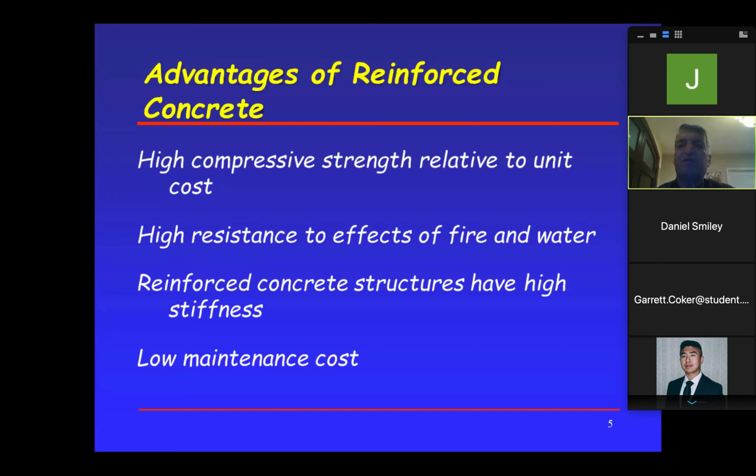And that's unfortunate for me because I like concrete. I'm a concrete guy. So we went ahead and built it with steel. Because at that time, China was booming and they were buying all the cement out of this country, believe it or not. So the concrete was expensive, steel was cheap. So that's why it was economical to do it with steel. So one of the considerations you will consider is the economy of the material. Do I build a building with concrete or do I build it with structural steel?